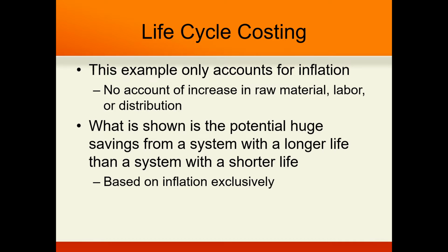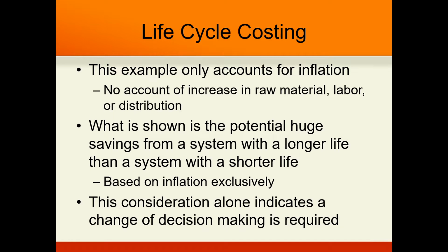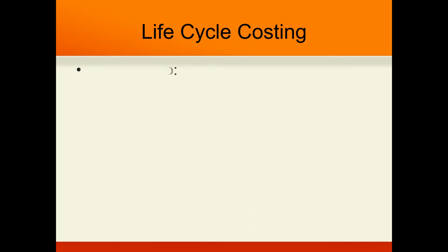This is based, by the way, only on inflation. I can't say that enough. But when we start in life cycle costing, adding all these other factors in, we start to see that this has got a significant impact. This consideration alone indicates a change of decision-making process. From our preventive maintenance to our building renewals, we're going to start looking at taking on systems that are a little bit longer in life, because it will gain value by shortening the amount of overall cost through that useful life of that facility or that building.